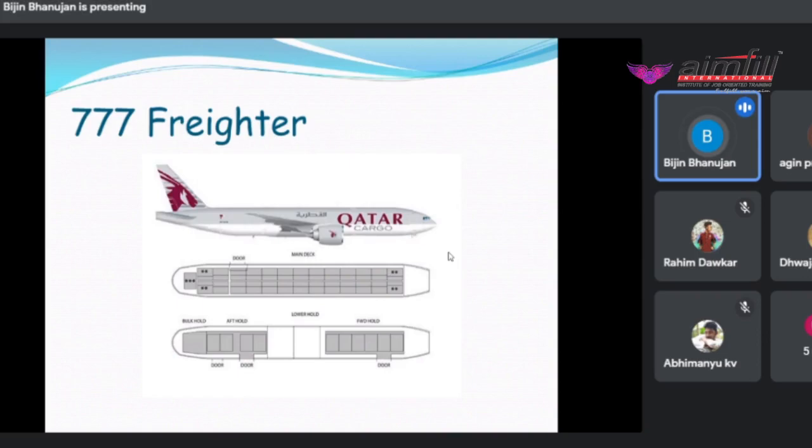So, what is a ULD? ULD is a container used to load luggage, freight, and mail on wide-body aircraft and specific narrow-body aircraft. So, it allows preloading of cargo, confidence the containerized load will fit in the aircraft, and efficient planning of aircraft weight and balance, and reduces labor and time in loading aircraft holds compared with bulk loading single items of cargo or luggage by hand. So, a unit load device is a container.